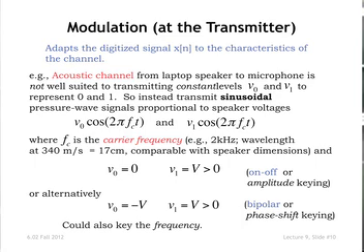Every time you want to shift from a 1 to a 0 or a 0 to a 1, you're going to change the phase by 180 degrees. That changes the sign, right? So it's fixed amplitude, and you step the phase each time you want to change. So this would be a natural way to do it. Why 2 kilohertz? Well, we know that this is the kind of frequency that a loudspeaker likes.